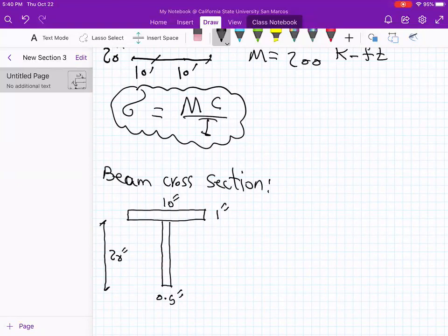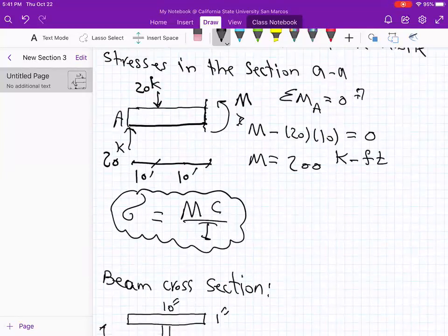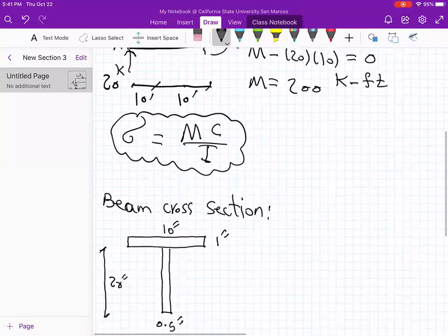Yeah, once we talk about the moment of inertia at the beginning, once we derive the formula, we have the integral of y squared dA. If you remember that one, then the moment of inertia is in the direction of M. For example, if M is in the direction of x, then we need Ix. If M is in the direction of z, we need Iz. If M is in the direction of y, we need Iy, right? So now the direction of the moment here is out of the plane, right? And if you look at this one, the direction of the moment is somewhere here.